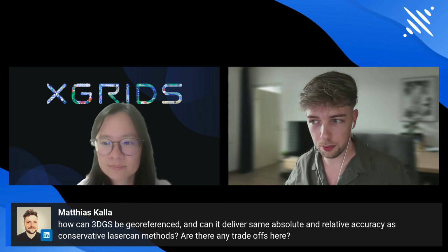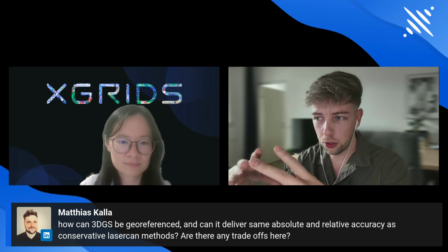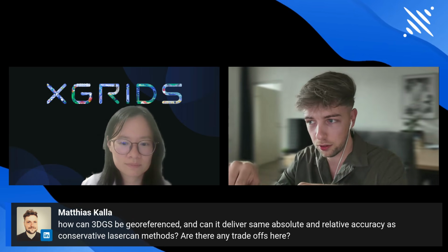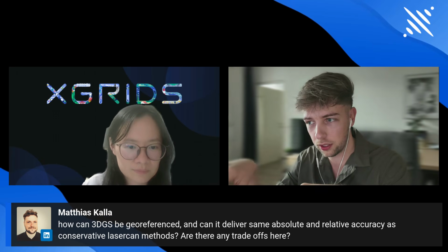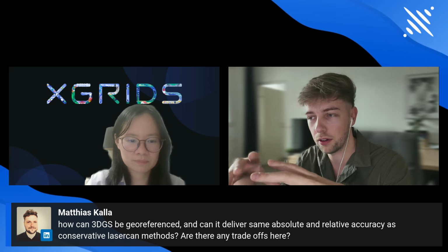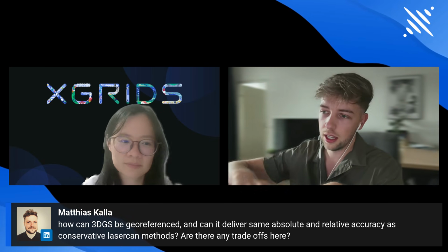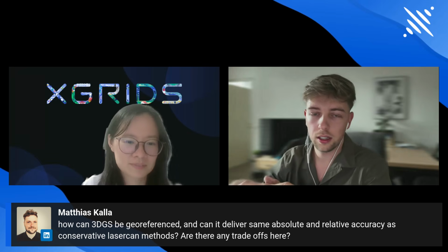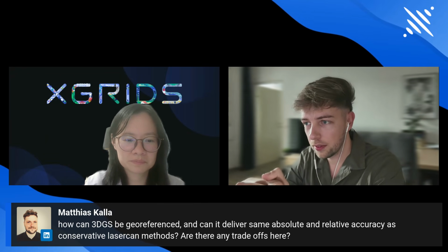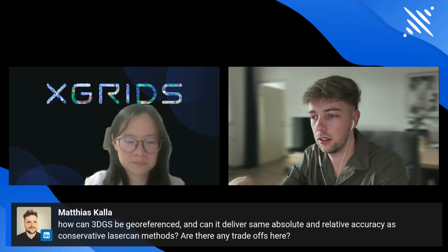The 3DGS is a local file and cannot be georeferenced, but you can reference the point cloud, because the 3DGS needs a local system. With point clouds, you can work with an RTK, connect with the satellite and import the GNSS data. Then you have the same location for a coordinate system.